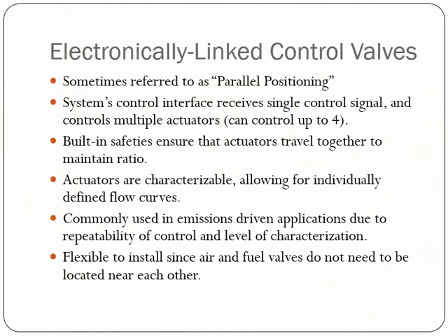It would receive your control signal from the temperature controller, and then based on a set of parameters that the burner technician would install or adjust, it would communicate and translate that control signal out to multiple actuators. There are certain products that can control up to 4, and I think there are even some that can control up to 8 or 10 actuators with one control signal.